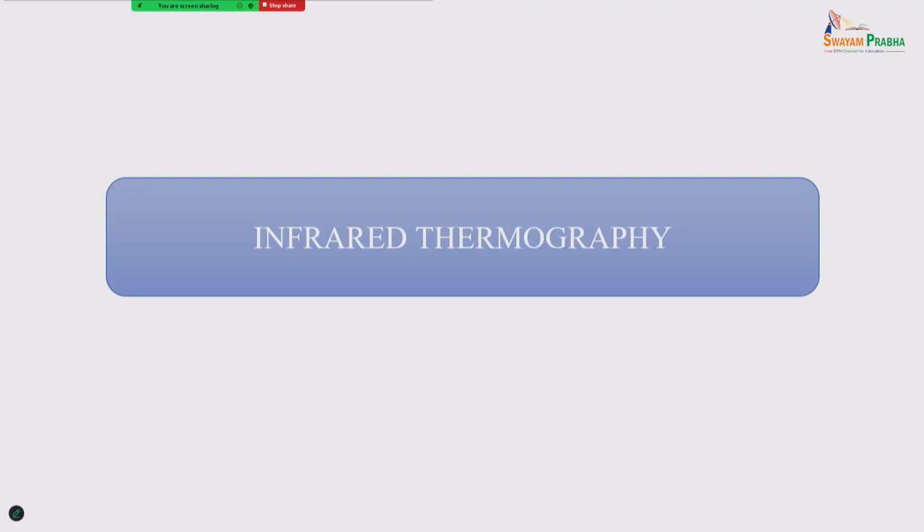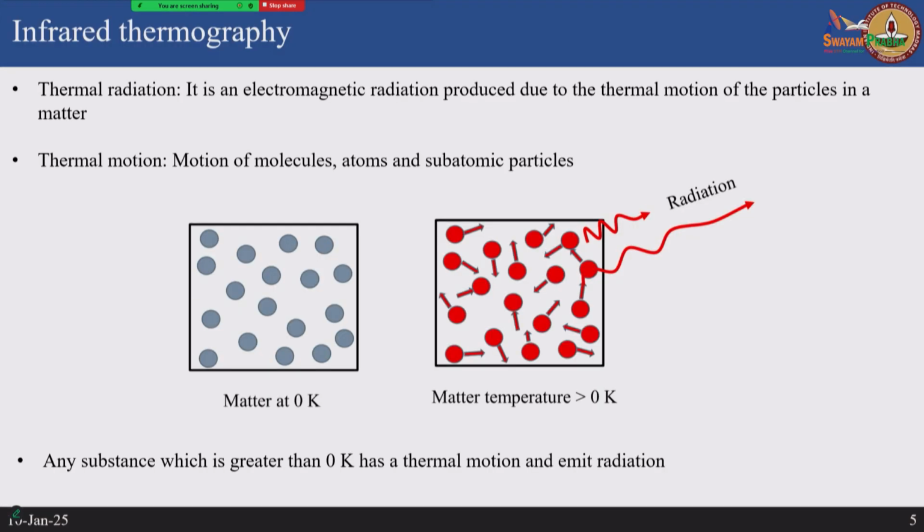So, this is a very advanced technique, especially used for droplet size characterization, but if you just want to measure only the flow field, then PIV itself is good enough. And coming to temperature measurement techniques, the most important thing that you need is an infrared camera if you want to measure temperature in a non-invasive method. So, we will talk about infrared camera to begin with before we get into the other techniques.